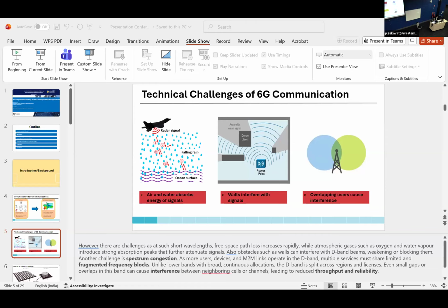I also applied master-slave boundaries to the opposite faces to simulate an infinite array of meta-atoms and hence represent a metasurface. And this is in the X and Y direction. This means that one cell or meta-atom represents the entire array. And then Floquet port excitations are used to excite the structure with plane waves, assuming it repeats endlessly in the X and Y direction, hence assuming a metasurface structure.